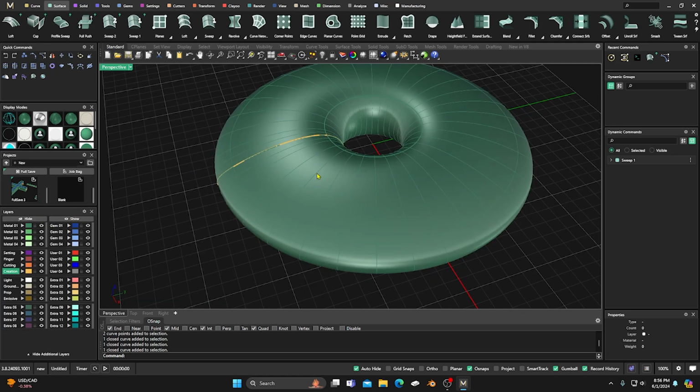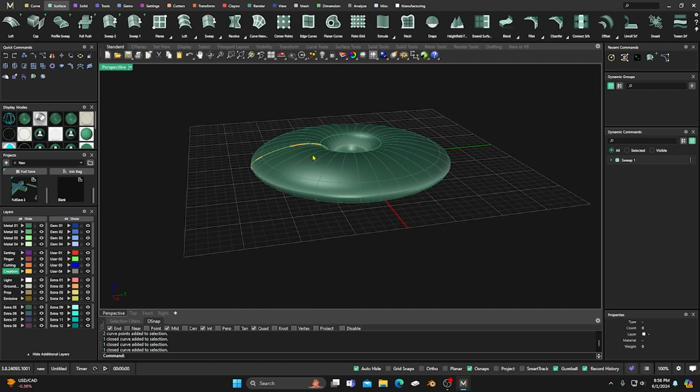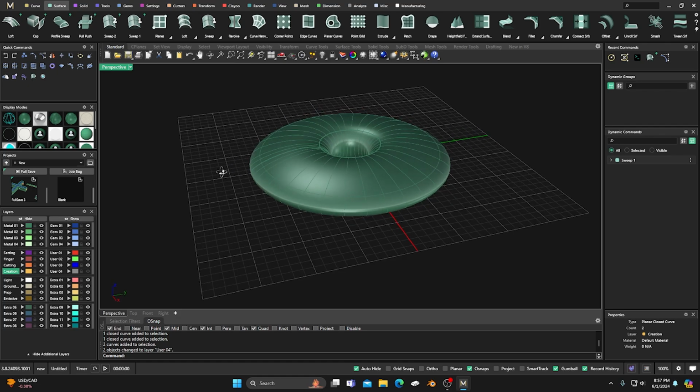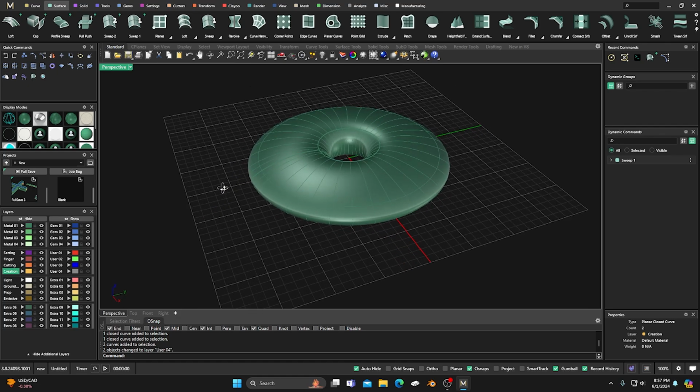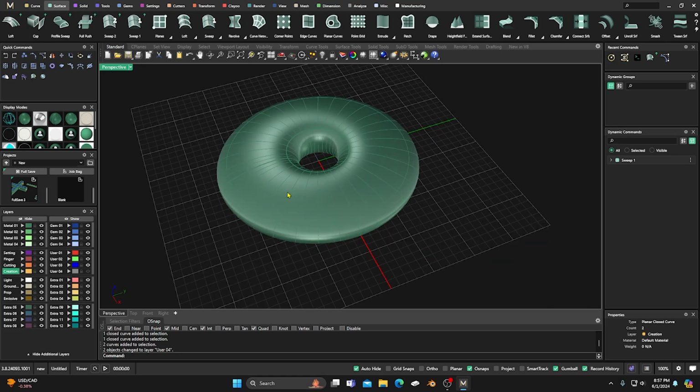And now we're going to end up breaking history, so make sure you get the shape that you want now, because we're going to break history on this. So I'm going to go ahead and select that curve, and I'll change it to gray and hide it, because we could possibly need it in future depending on what you're doing, because you can use that curve to make another surface if you need to for whatever reason you want, right?